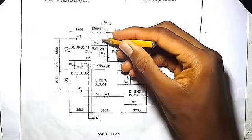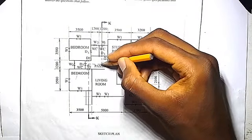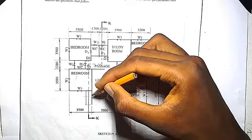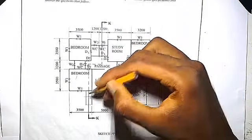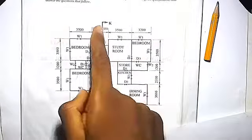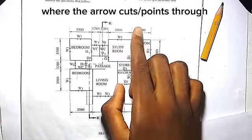So when we are looking to the front towards the building at this part here, it's sectioned from this window, from this block here down to the passage here, then it moves to this other part and it runs through the bedroom. That is how they sectioned it. So this part is being cut out. But what will be seen is the rest of this part. The part that we are going to look at or use to draw is the part where the arrow points towards.